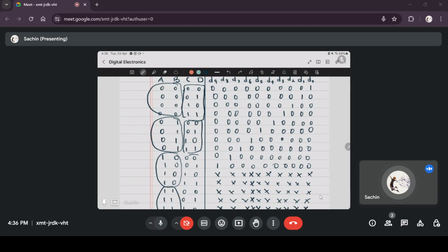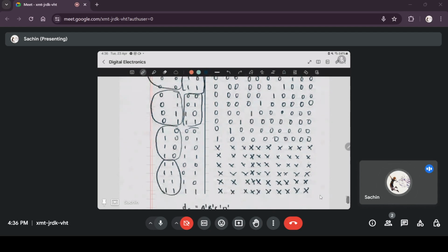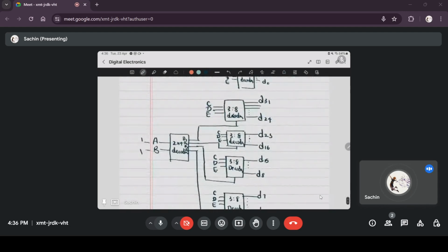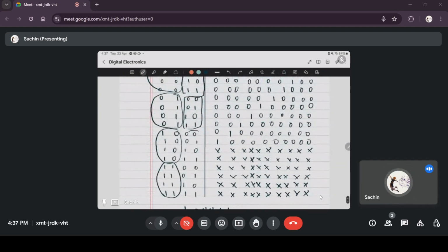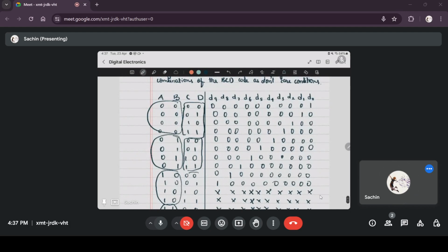So what you do is you have a decoder for each of the remaining bits that will decode to one particular line based on the input at the remaining bits. So we have here four such decoders, and which among these decoders has to be selected depends on the value of A and B. So if AB is 0 0, you select the first decoder.